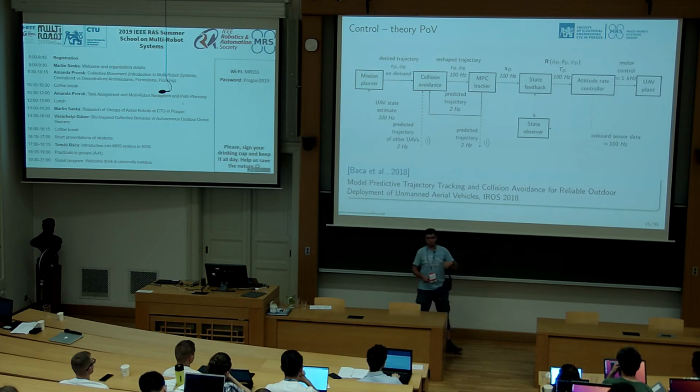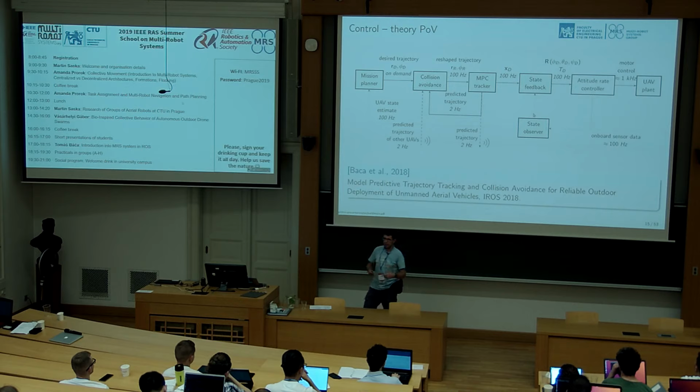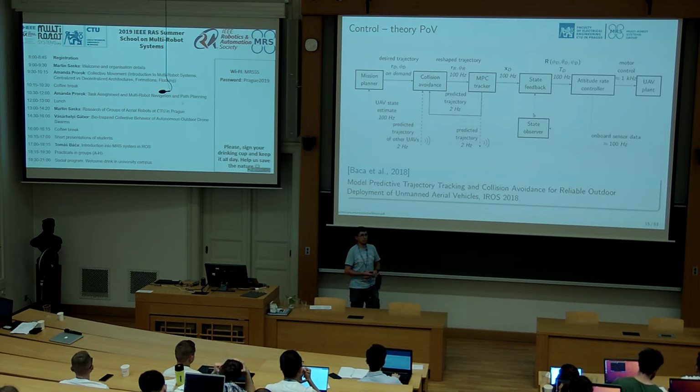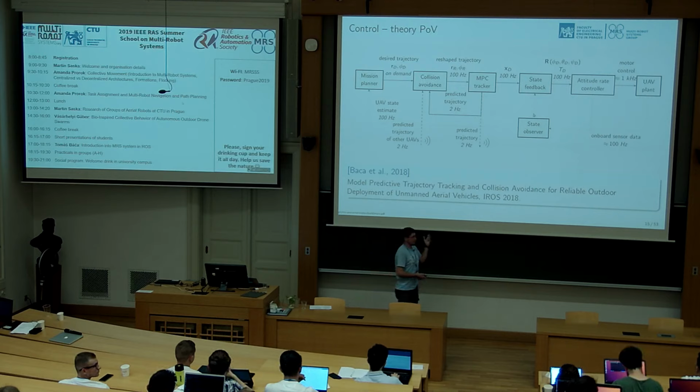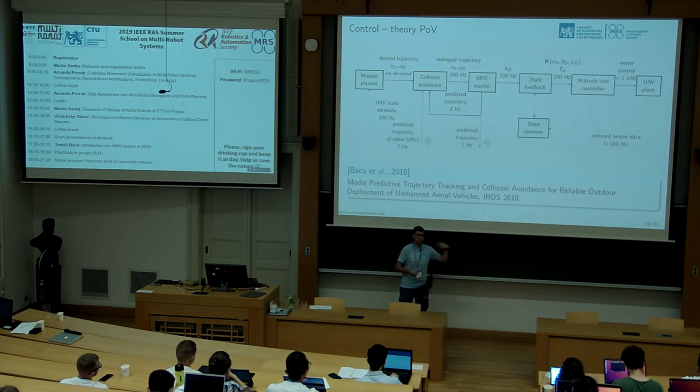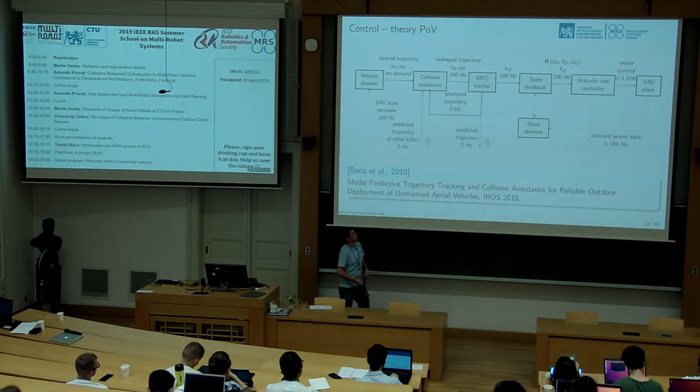So when we need to control those angles, we supply an attitude rate reference to the Pixhawk, and the Pixhawk takes care of that. So let's say we want to rotate by 1 pi radians per second. We tell that to the Pixhawk, and the Pixhawk just does that with the drone, and the drone flips and rotates.